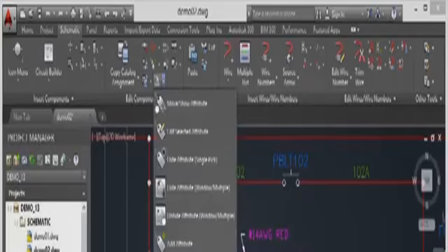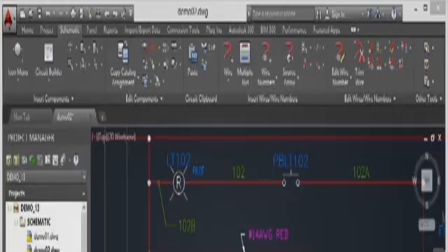If I click now, 1, 2, 3, 4, I'll go up to 0.95, which is the default. I'll then go here, 1, 2, 3, and keep going until I get to the 0.95. There we go. Press enter to finish. So now it's back to where it was before. So that stretch and squeeze allows you to rationalize and either make the text smaller or bigger depending on what you need to display on your AutoCAD electrical drawings.